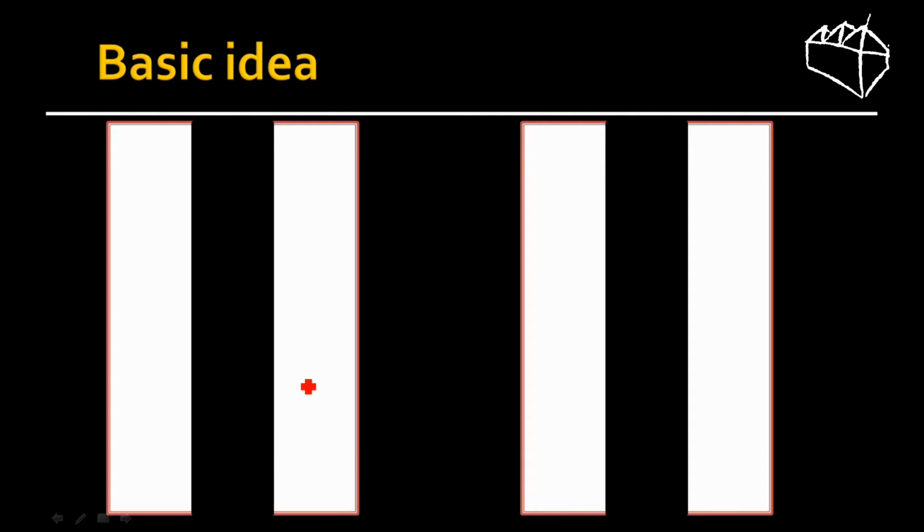If it's on the white, it would receive a value of 100. And if it's perfectly on the edge, it would receive a value of 50. Now we have to write a program which lets the robot decide which actions to do depending on which values it gets from its color sensor.